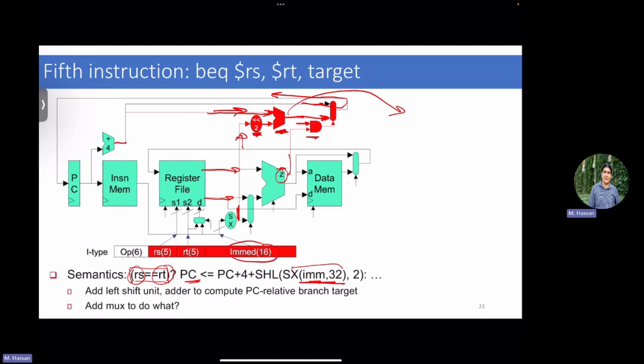Opcode to say that this is a branch, because the zero flag can be triggered if you have a subtraction operation, right? So you don't want to really jump if you just did a sub and the zero flag is suddenly triggered. So your condition enabler here is you have a branch and the zero flag is enabled, right? So in that case, I take the new address and then load it to the program counter. Make sense? So this whole circuitry here is just to enable the branch.